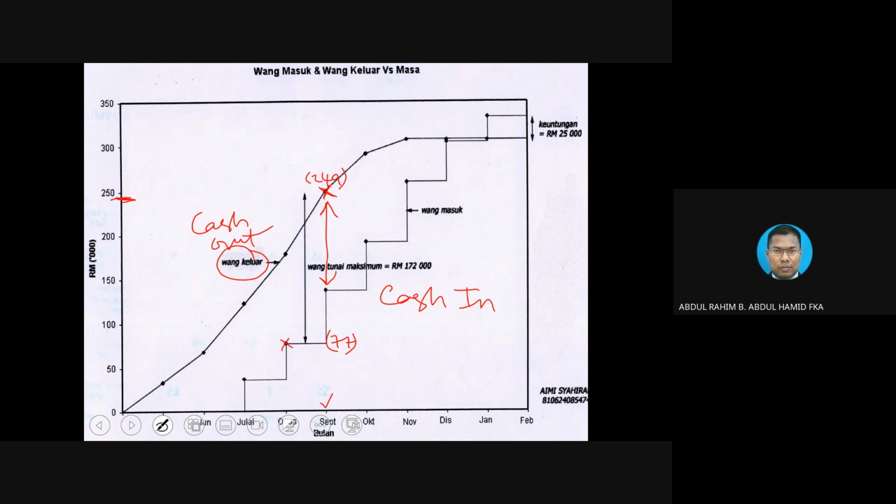If I do that, then it is not a lot. We are concerned with the contractors having difficulties. So which one is more difficult? Is it a lesser cash requirement or a bigger one? So that's why the cash required is basically the cash out on that particular month minus the cash in on the previous month, because our assumption is that the money that the contractor has in the current month is based on last month's payment. And you notice this is the amount here happening on 9.